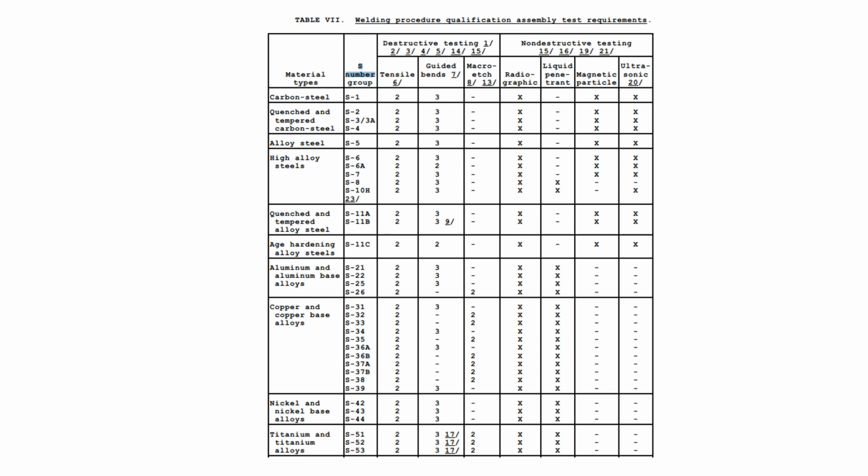That's all they are. It allows us to write a welding procedure and use an M number or a P number and say, okay, I'm going to do M number 1. That's all the carbon steels. Or I'm going to do P8 materials, which are austenitic stainless steels, your garden variety 316L stainless steels.